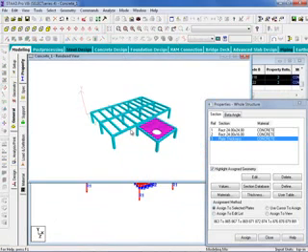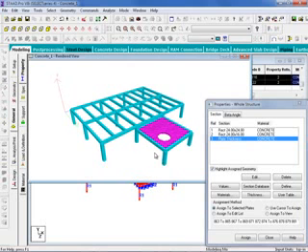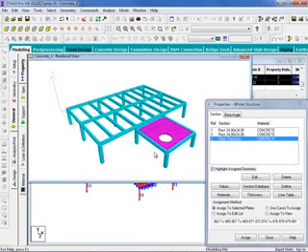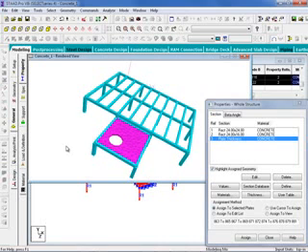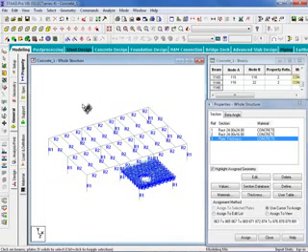When I select this, I can see the model in 3D with the appropriate scaling for the sizes I assigned. This might be a good way to make sure your members are oriented correctly, and I can also spin it around to make sure something has been assigned to every element in the model. When you're done reviewing the 3D rendering of your model, you can go ahead and click the X, and we are now finished assigning properties to this model, and we're ready to move on to our next step in our workflow.